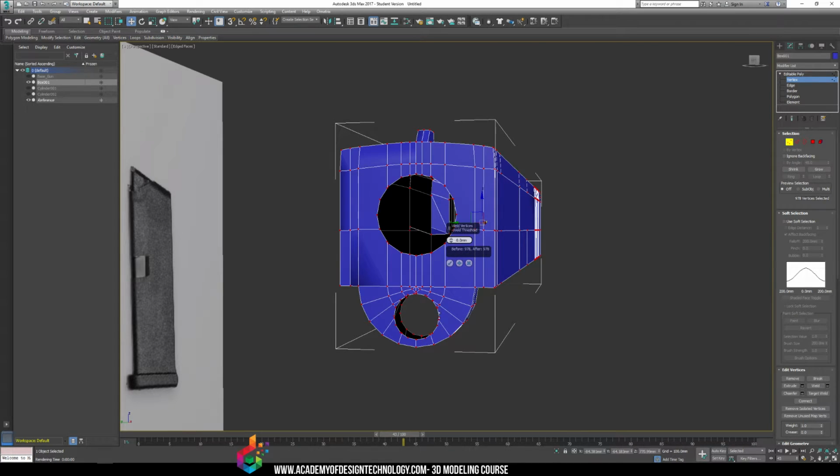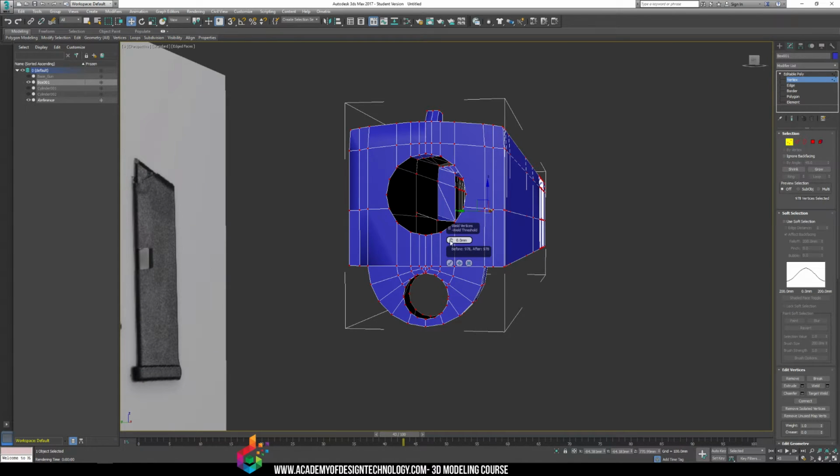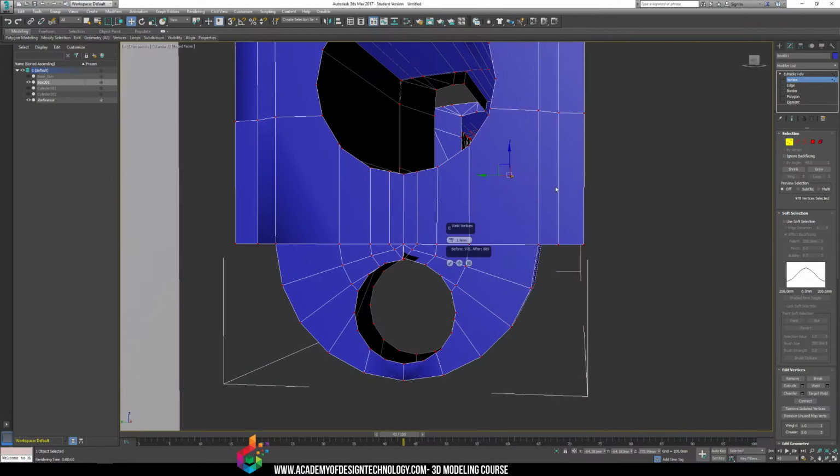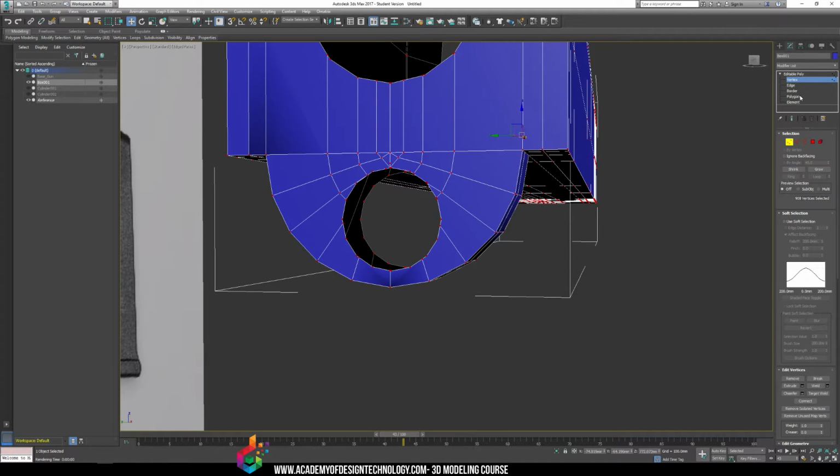I'm going to preview what it looks like when I weld at 0.1 millimeters. 0.8, 1. You can kind of see how everything welds. And I usually like to pick just small amounts. And right now we're at 1.9, and you can see we run into issues where vertexes are overlapping each other. So don't worry about welding too far apart. I'd always suggest to work in 0 points. So 0.1, 0.3. So we're at 0.3 right now. And it's just a matter of changing your smoothing groups.